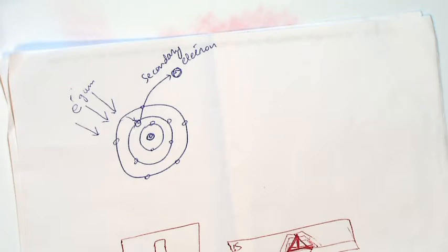After that you can build a contrast of the surface, and you can generate a pattern with some image processing. That's how you can see the small features on the surface. You can also characterize the material: it shows a different contrast when, let's say, you have gold and silicon dioxide. You'll have more ejection from one or the other based on the material properties, and that can also give you a contrast to see how your surface looks.